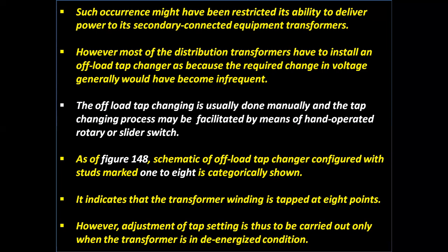Most important point. The off-load tap changing is usually done manually, and the tap changing process may be facilitated by means of a hand-operated rotary or slider switch. As of figure 148, a schematic of an off-load tap changer configured with studs marked 1 to 8 is shown.